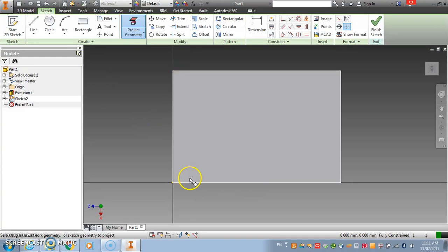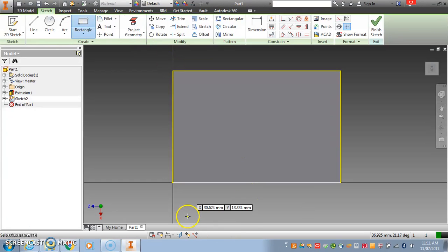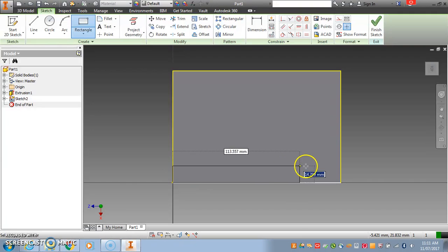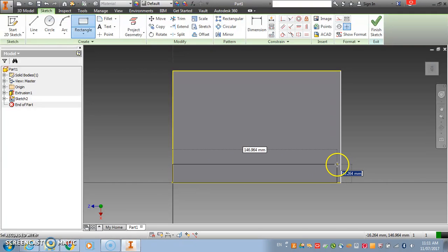So I want to create a wall. Okay, so this is my top view. I want to create a wall at the side here and there. Okay, so I'll draw one by one. So first thing, I will click on rectangle. I will bring it to the corner so that there's a green dot indicating that it is exactly at the corner. So I click once, let go, and after that I bring it across to the other side until I touch the other side. I click again.